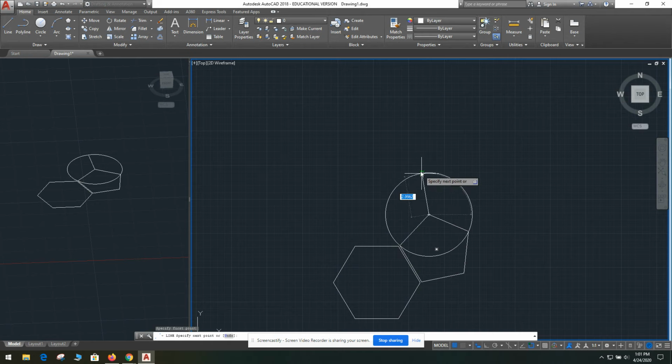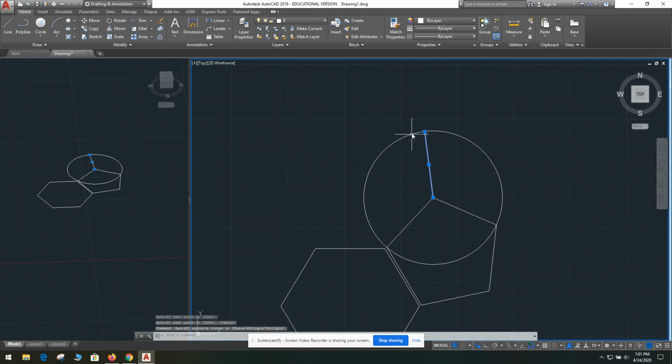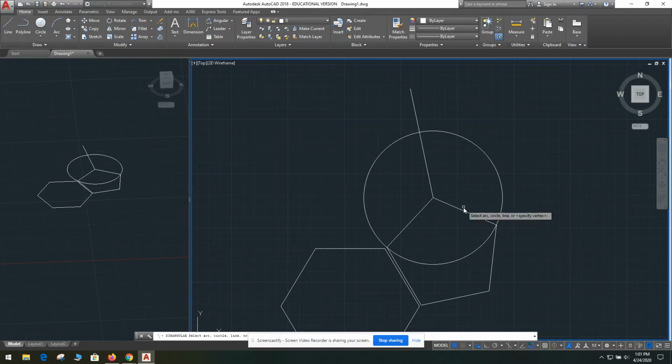So, and then what you can do is if you want to just be kind of not sloppy, but if you want to be quick about it, say you bring out your line like this, you can come in and just do an angular measurement, 125, right click, do it again, and come over here and do it with 27. Okay, so I'm not quite there.